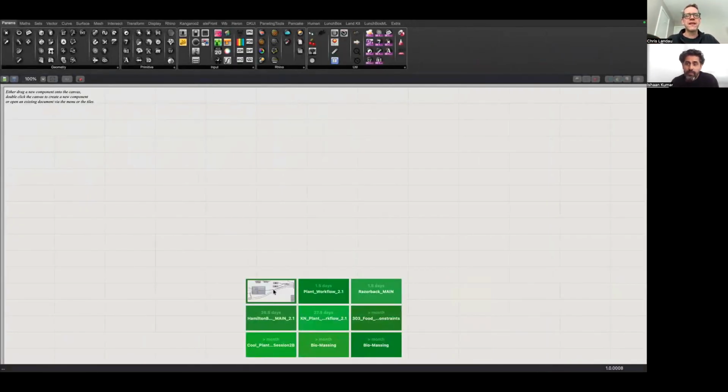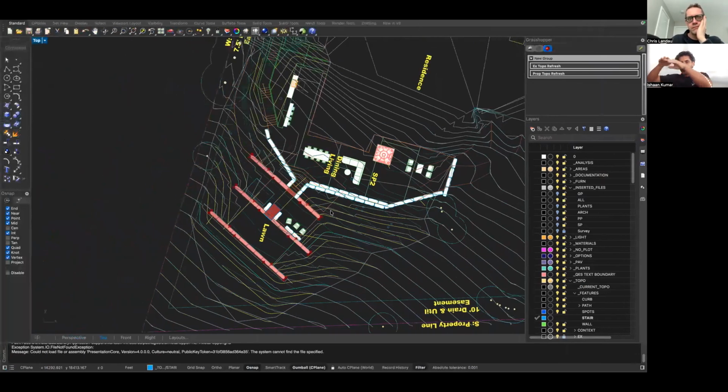I think one of the things that I would critique of the process that we've done is that, even when you did the first break line, you tied it to a contour and you went into the side view. I thought of this as, all right, I know the finished elevation of the first floor, and I know that I can go up a max 30 inches. So those datums were always very clear to me, and those break lines of those walls, you move them in the Z value, and right now we're just moving things fast, but they can be hyper precise, which is probably where I'm more comfortable.